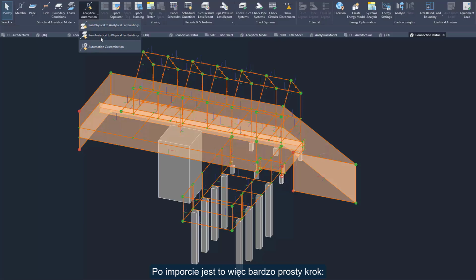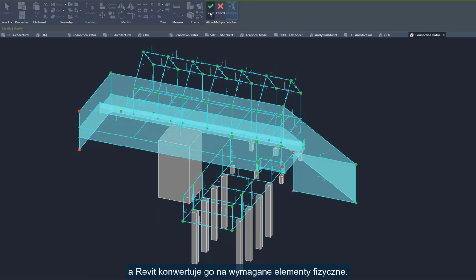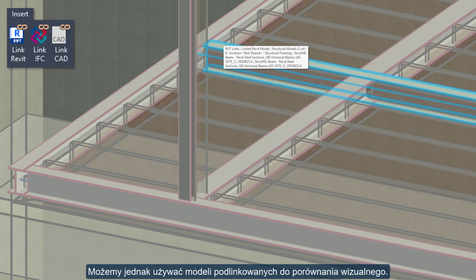So after import, it is a very simple step. We select the full imported analytical structure and Revit converts it into the required physical elements. Now, a few words about change management. In Revit, there is no dedicated change management tool, but we can use linked models for visual comparison.